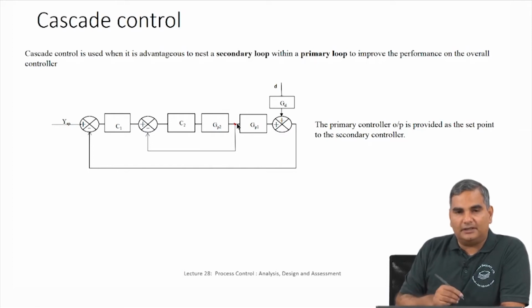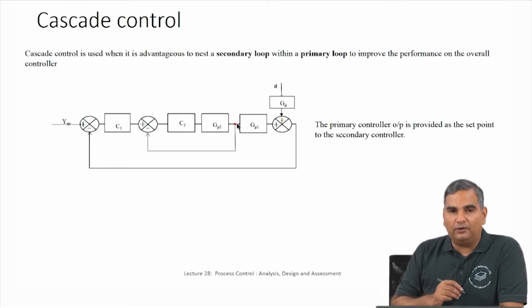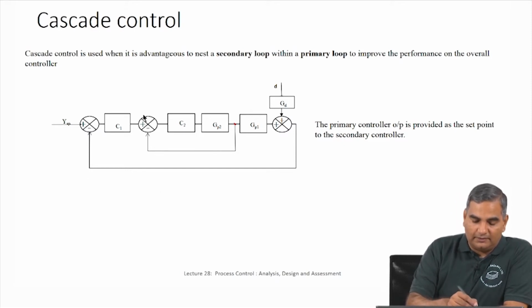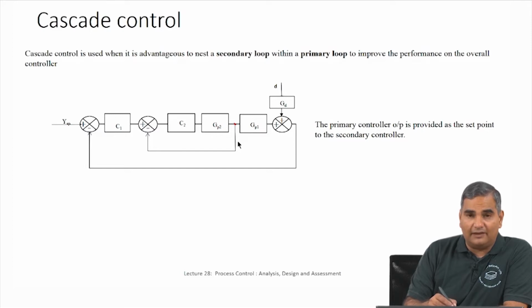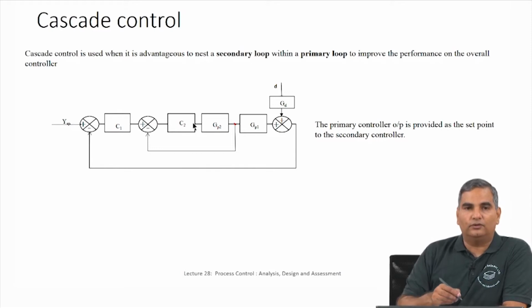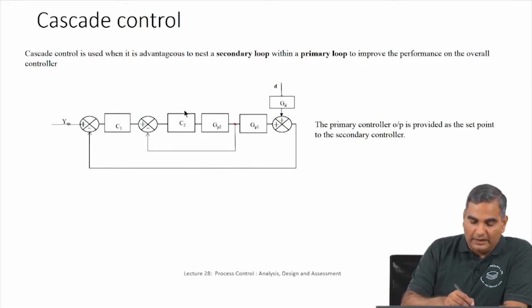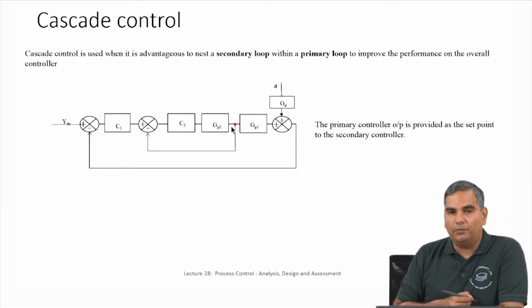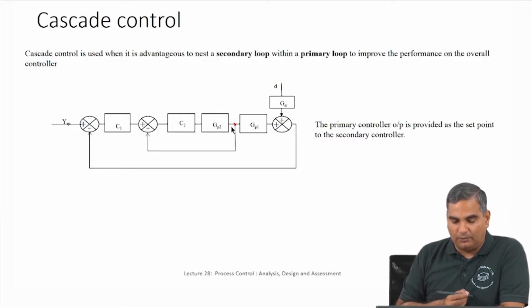But if I actually measured a stem position, then what you can do is you can give a set point to the stem position and introduce another controller, so that this controller looks at the set point for the stem position, and now since I have a measurement, I can compare that measurement against the set point and then close the loop inside. Okay. So, there is one inside loop and another loop outside, and this inside loop is possible only if I am able to measure the output of the valve dynamics, which is the actual position, right.